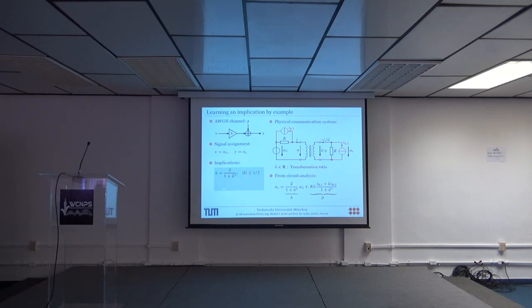Going through that, we see, first of all, that our channel coefficient in magnitude is limited by 1/2, and that maximum value is reached when the turns ratio is equal to 1, when it's a 1-to-1 transformer. But the funny thing is, the noise variance will depend on the channel coefficient. It's not independent of the channel coefficient. And when we then look at SNR, as I have defined it, and start out with the maximum channel coefficient of 1/2, we get some signal-to-noise ratio. Whatever that number A may be depends, of course, on how large I make the generator voltage. But anyway, if I now reduce my channel coefficient from 0.5 to 0.25, SNR goes up and not down. And that the standard theory would never predict.